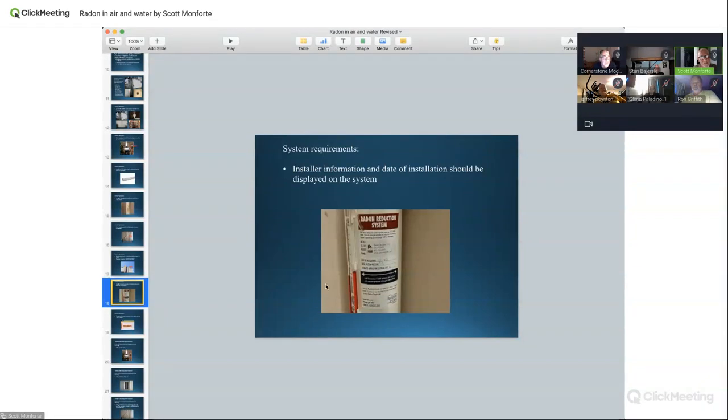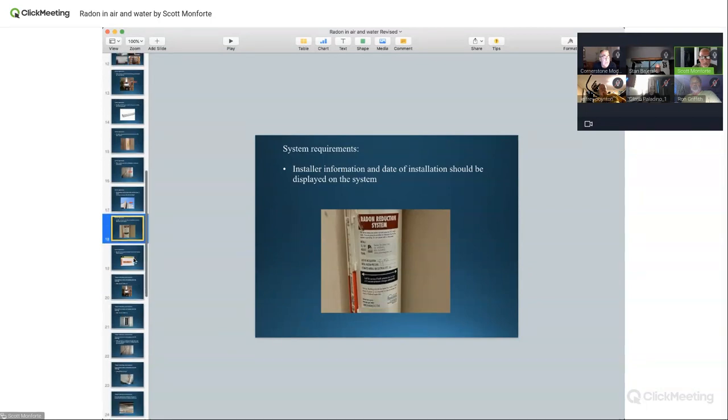The label, everything should be labeled. It should be properly labeled. There should be a manometer on there. The pipe should go above the roof line if you see it. If you think it's really close to the window, now there's a picture in here where the window goes right up to the soffit. That's where I would extend it a little bit higher. Nobody today opens the windows with the whole house fans. Maybe they do, but who opens the top part of their sash? Most of the time everybody's got their AC on, but it's supposed to go above that window.